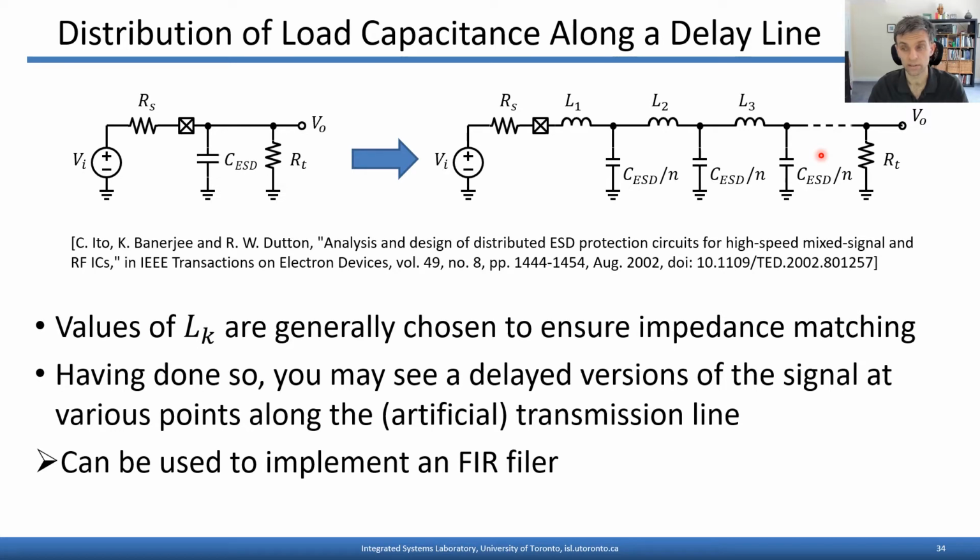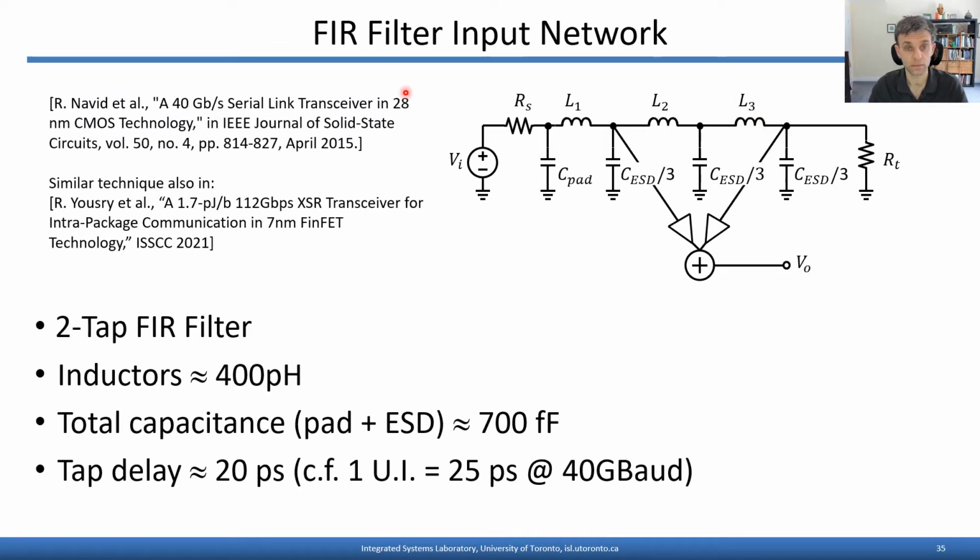You can essentially take weighted sums of various voltage waveforms along this ladder and implement a finite impulse response (FIR) filter here. And that's exactly what was done in this paper from 2015. A similar technique was used in this paper from ISSCC 2021.